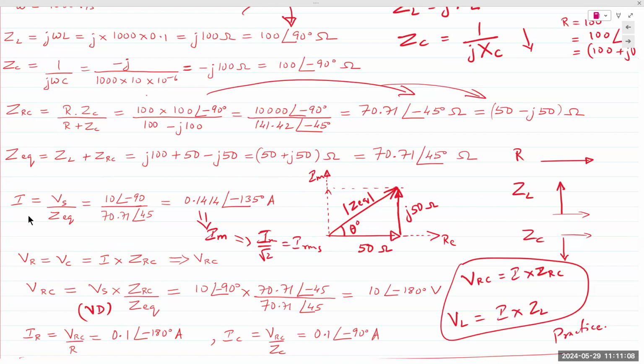So we can take two approaches. The first approach is basically find all the individual powers, R, L, and C, and then you add it all up. Law of conservation of energy states all of the power delivered by the source is absorbed by the components, by the loads. So if we find or determine all the individual powers and add it up, that would give us the total power delivered by the source. Make sense? So that is the approach for the first half.